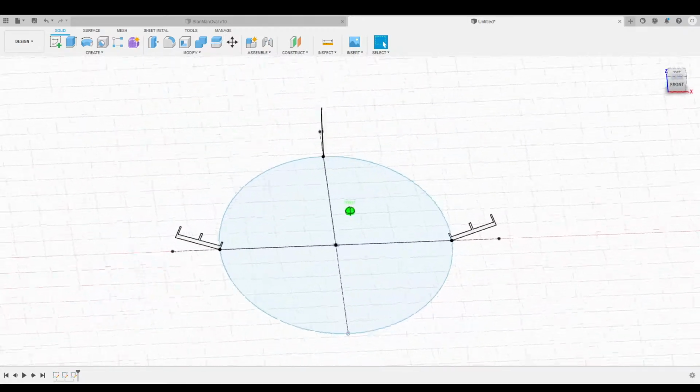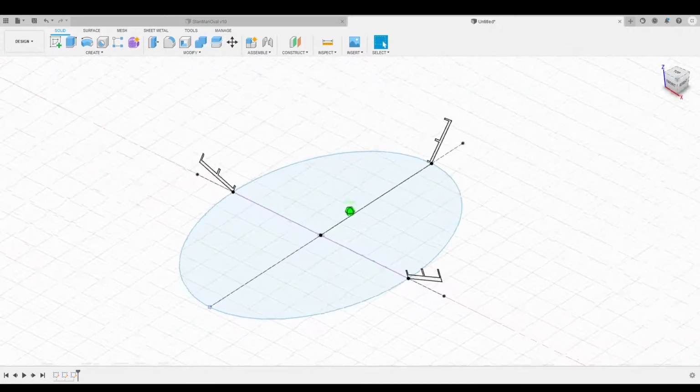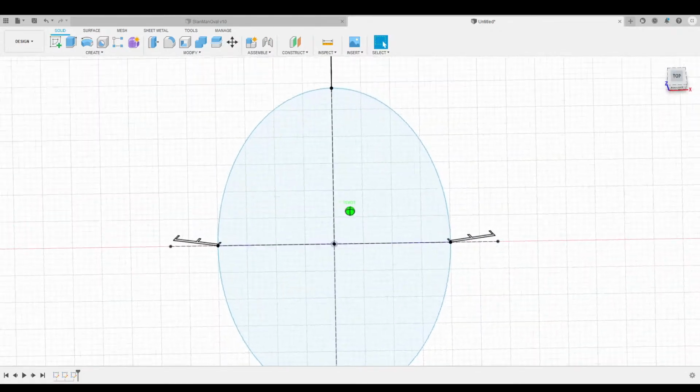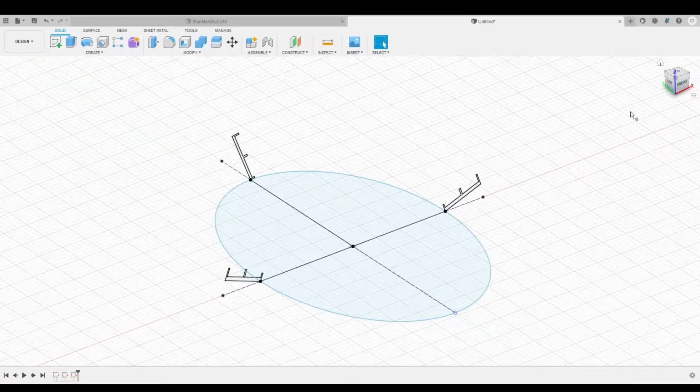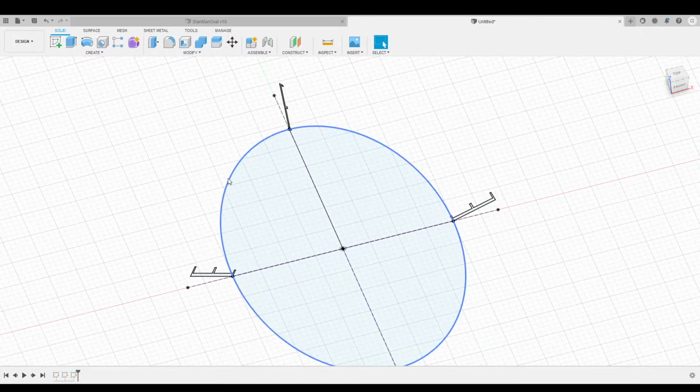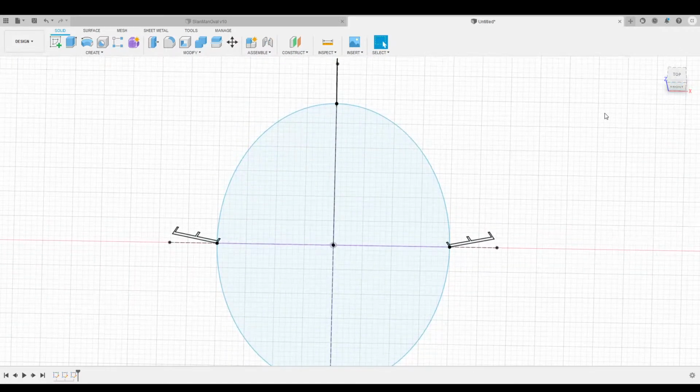So this is where we start deciding how does this thing actually look, because we need to be able to describe to Fusion what we want. So our entry angle is 20. Our highest angle is 50. So somewhere in this general vicinity, we're going to have to pass through all the different angles between there. And so we're going to pick maybe 30, and we'll go over this too, but a certain distance away from here, we need to be able to sketch another profile at a slightly less angle than here, but more than here, and hope that when we do the loft, Fusion will be able to figure it out. And that is an interesting thing to have to figure out.